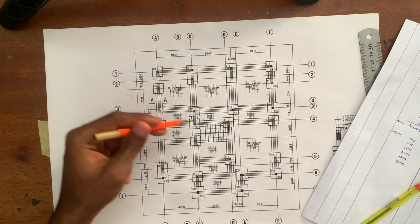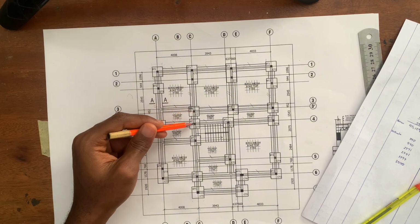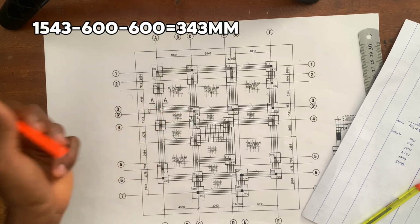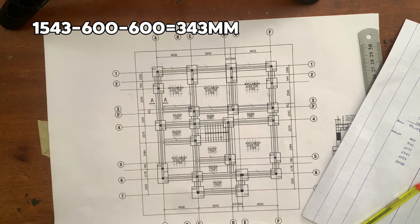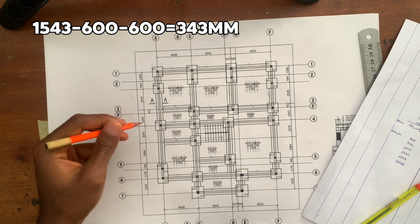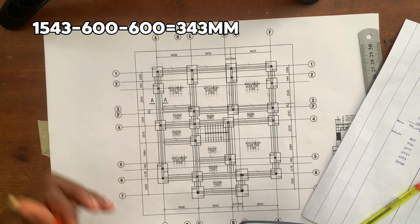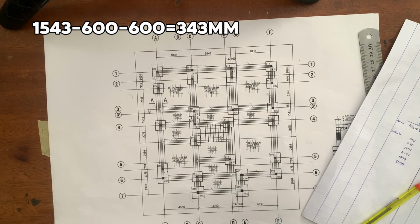Since we know from here to here is 1543, we can now minus half of base type 1 from both sides. We know that the dimension for base type 1 is 1200 by 1200. So we can now minus half from both sides from 1543. 1543 minus 600 will give me 943.